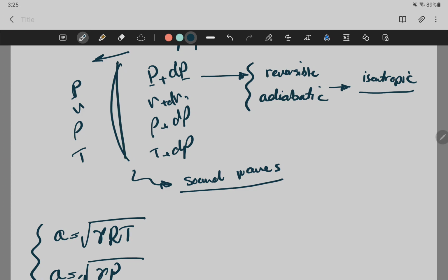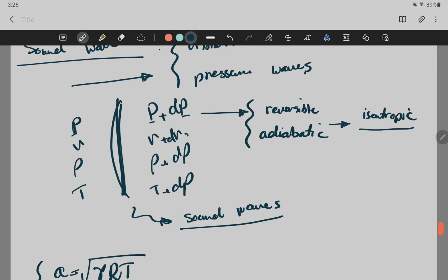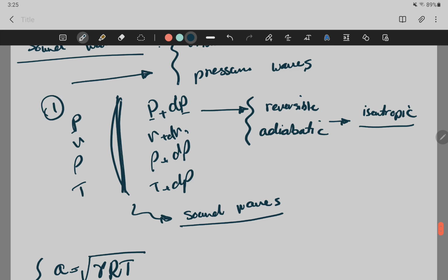Let's say this sound wave is the thing that is fixed, and this air is moving, passing through the sound wave. We have the sound wave fixed here, air is passing through it. That's the assumption we always have when we do aerodynamic analysis. We assume the aircraft is at zero speed and the air around it is moving, right? Which is a very valid type of analysis. It's not even an assumption, it's just a different type of analysis. Okay, let's apply the conservation of mass. How did we calculate the conservation of mass? Let's say this is your point 1, this is point 2.